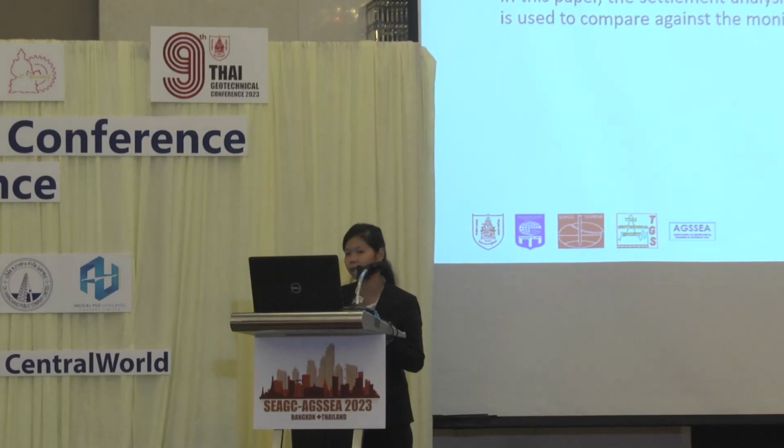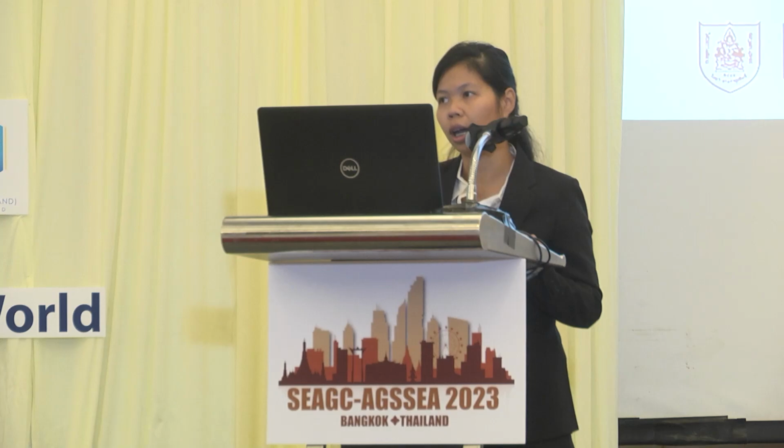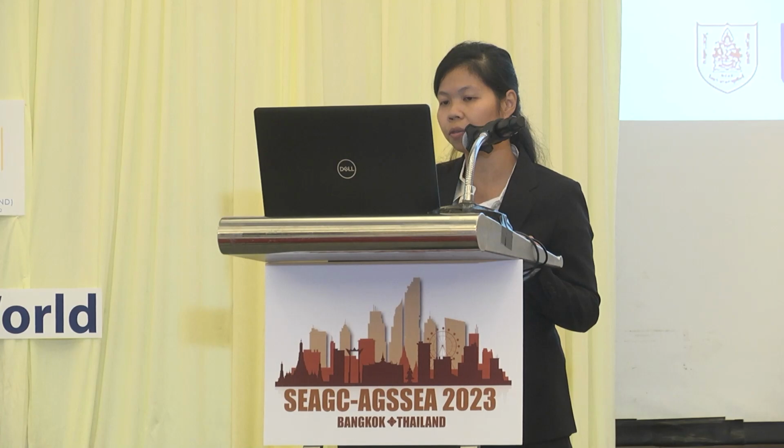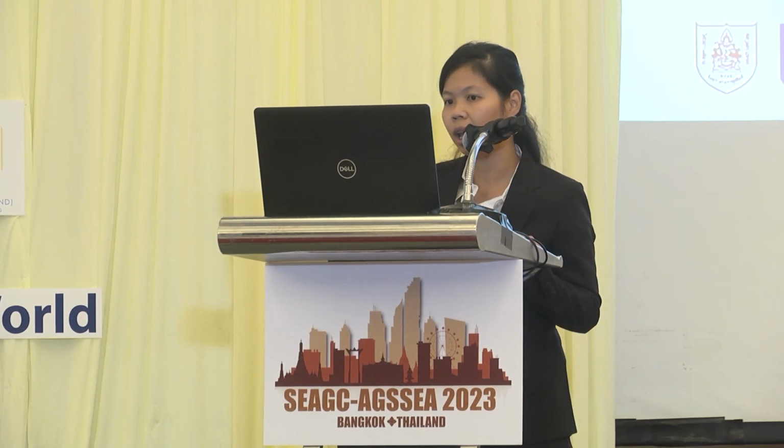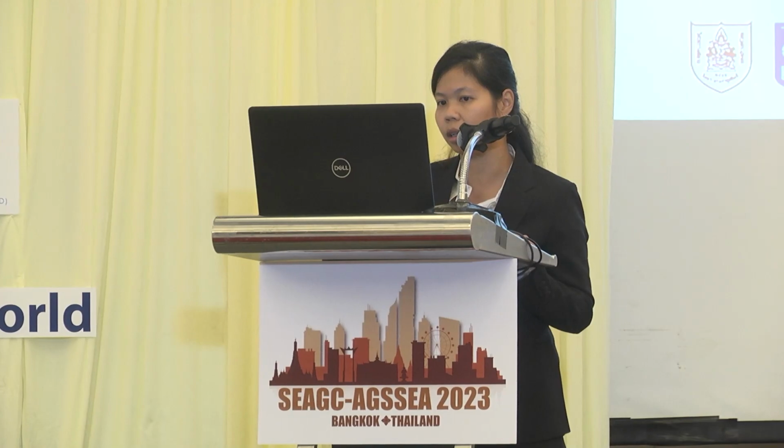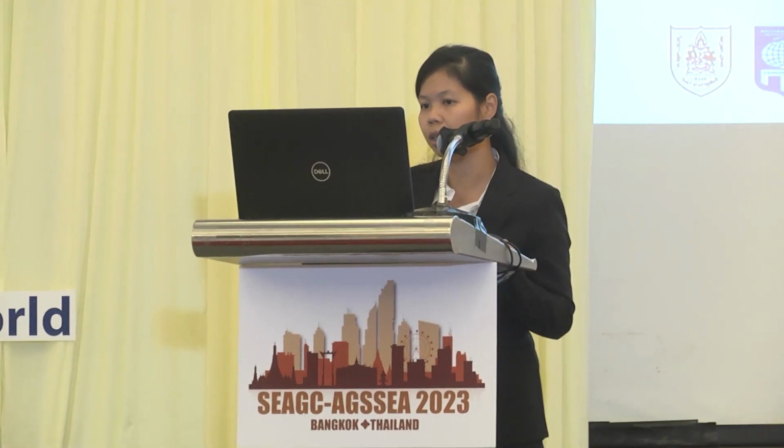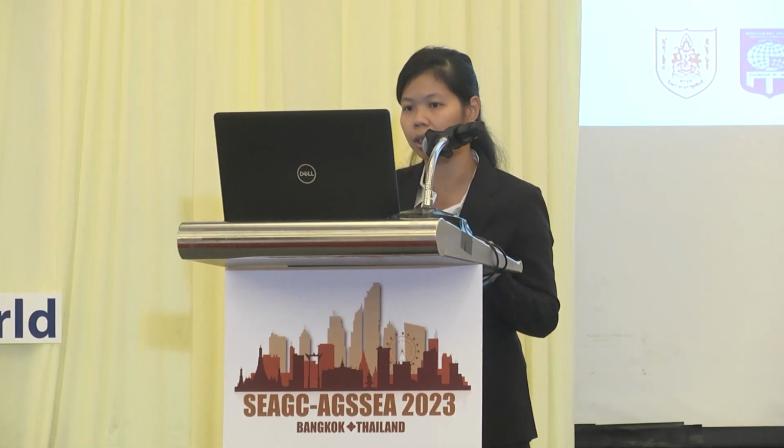Normally we do HDD where the open cut is not possible due to the site limitation or also not permitted by the authority. So HDD would normally raise a concern on the potential ground loss issue, which can result in ground settlement. The calculation of the settlement involves estimating the volume of soil that will be displaced during the drilling process and determining how much settlement will occur as the result. In this paper, we will discuss the settlement analysis from both empirical and numerical analysis, used to compare against the monitoring data.